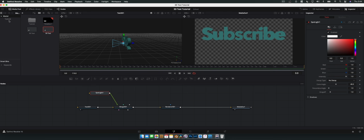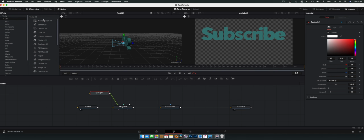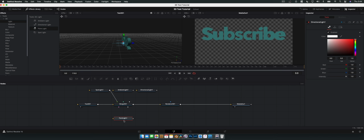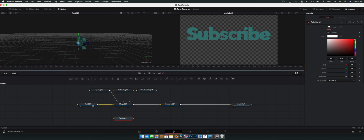Let's go to the media pool, let's go to the effects library. We're going to drop down 3D, we're going to drop down lights, and we're going to add all the different lights: ambient, directional, and point. All right, and what we're going to do is connect them all together, and have a look at how they all work.